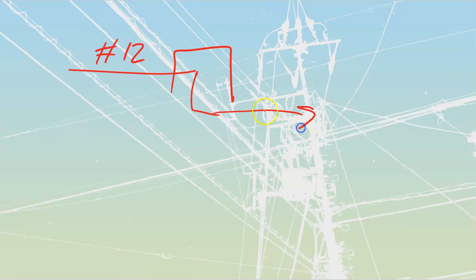That would be where you've got your ceiling outlet box, you're coming into there with number 12, and then you're allowed to tap down into 14 and go through each of those fixtures, but you have to add up all of those amps and make sure that they're not going to be above the rating of a number 14 out of the 60 degree column.